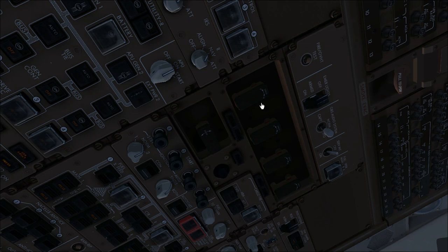We can go down. APU bottle discharge light extinguished. Here the APU fire switch is in. Cargo fire discharge light is extinguished, as you can see, and the cargo fire arm switches are off and out. Okay. Forward and after lights are extinguished into the two switches. This is fine. We can move to the engine start panel.